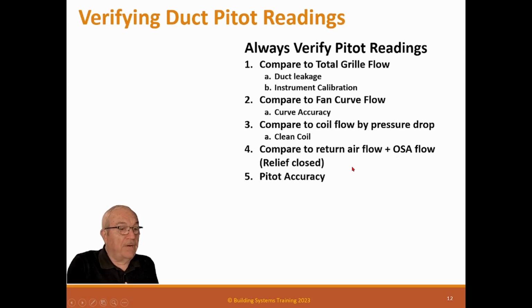The pitot accuracy itself is what we're trying to determine. Was this an accurate pitot or not? You don't want to blindly trust your pitot. It's trust and verify, because the pitot could have an accuracy problem. It could throw off the thought process in reviewing your balance. So you want to make sure you have an accurate pitot.